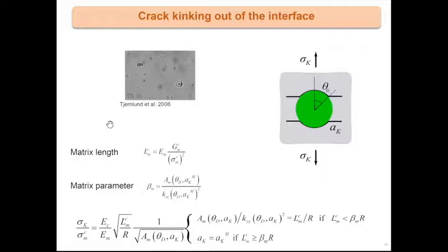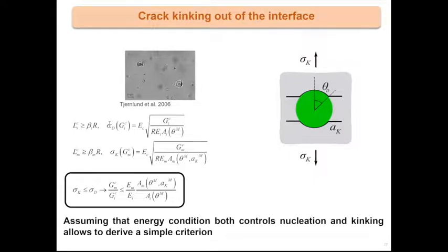So we introduce now the matrix length with the parameters of the matrix, the fracture energy of the matrix, the matrix strength. We still have a structural parameter, and we obtain exactly the same kind of situation with energy dominated situation, stress dominated situation. And it can be used to analyze this kind of situation.